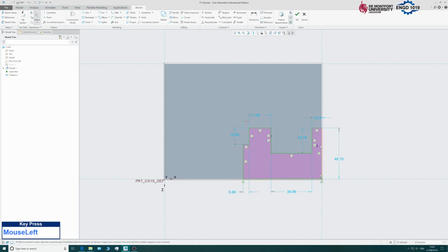Okay, so I'm going to first off start by setting the height here. So this should be 50. Okay, this depth here, it's not actually specified on the drawing. You could calculate it, so you could say it's 50 minus 20, so it's 30. But what you can do is override some of the auto-generated dimensions. So if you click up here on the dimension tool, I want a dimension from here to here.